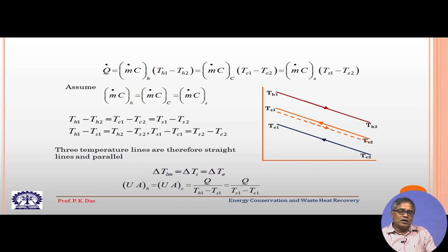with the outlet temperature of the hot fluid stream and the outlet temperature of the cold fluid stream. Assuming that in most applications the inlet temperature of the hot fluid stream and the inlet temperature of the cold fluid stream are known quantities. And of course, the heat exchanger characteristics like UA are a known quantity, and the heat capacity rates are known parameters.